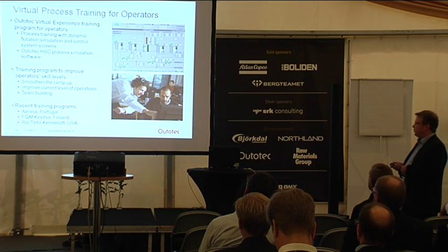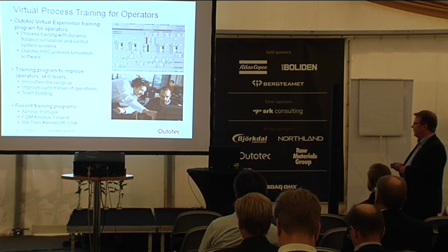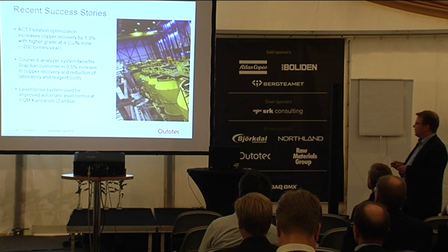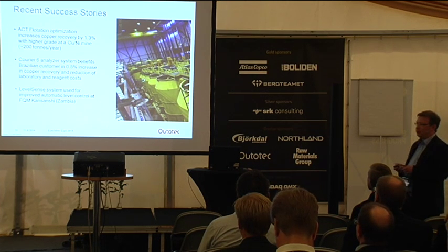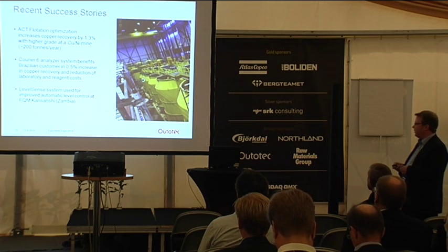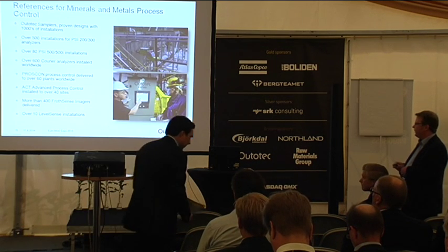The training for the operators is very important, and we have a virtual process training for the operators available, running our HSC process simulation, dynamic simulation, in the background. It has been implemented successfully at some sites. And recent success stories for flotation optimization: in a copper nickel mine, an increase of recovery by 1.3%, about 200 tons more copper each year. With the Courier 6 analyzer, a 0.5% increase in copper recovery and reduction of the laboratory and reagent costs. And the level system is used successfully in automatic level control in Kansanshi, Zambia.